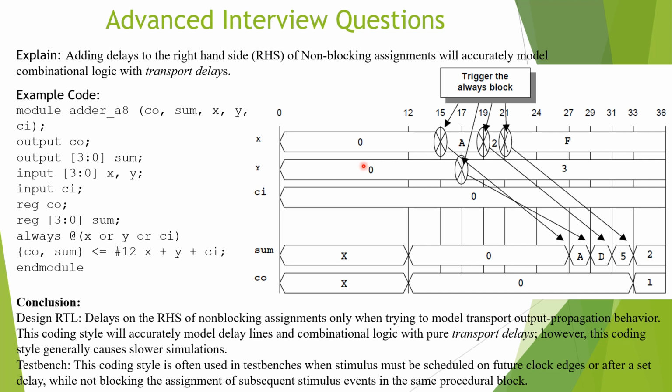When you're writing a test bench, this coding style is often used where stimulus must be scheduled on future clock edges or after a set delay, while not blocking the assignment of subsequent stimulus events in the same procedural block.